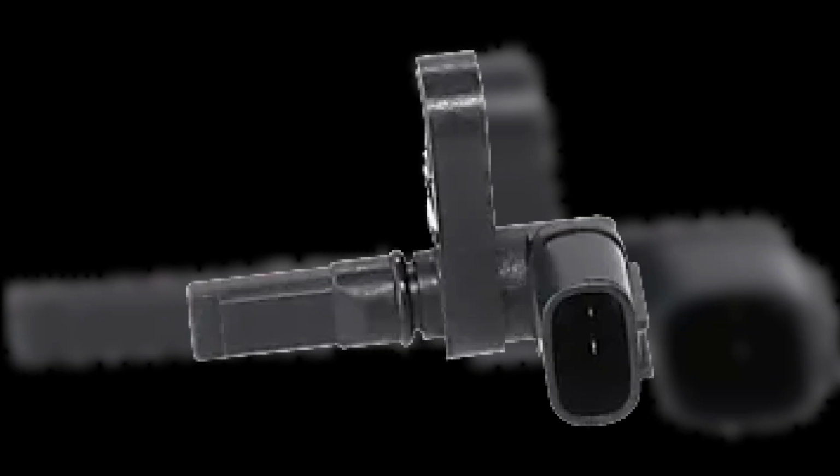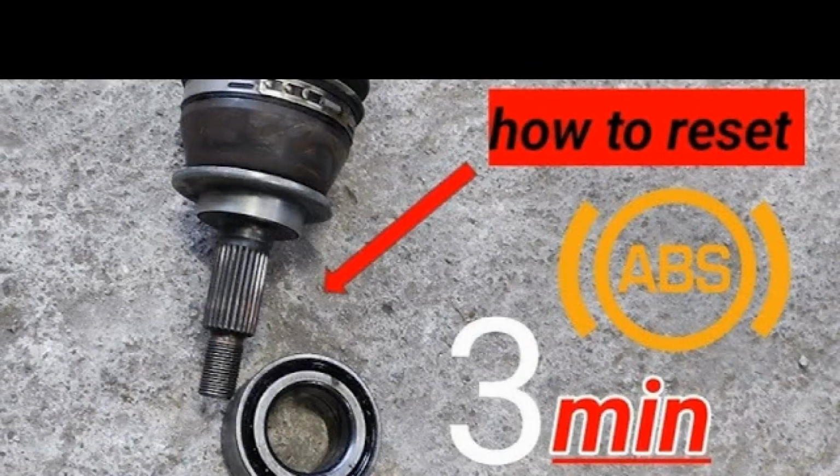Close-up on wheel speed sensors. Wheel speed sensors are essential components of the ABS, anti-lock braking system, and other vehicle safety systems. Here are some important points to consider regarding these sensors. 1. Sensor location. Wheel speed sensors are generally located on the outside of the wheel hub. They are positioned to detect the wheel's rotational movement. Wheel speed sensors can be of two main types: inductive sensor, consisting of a magnet surrounded by a coil of wire.